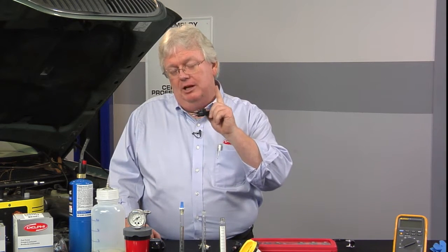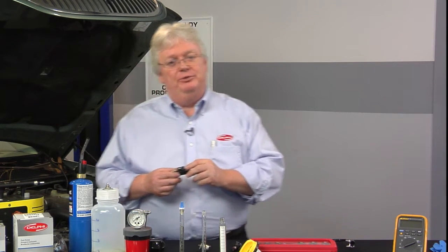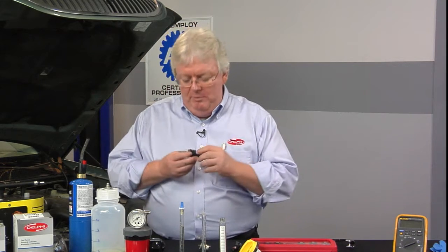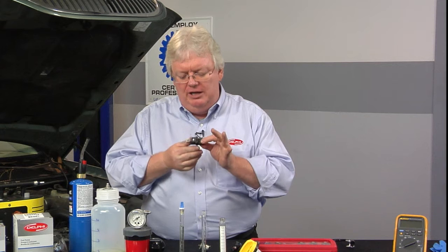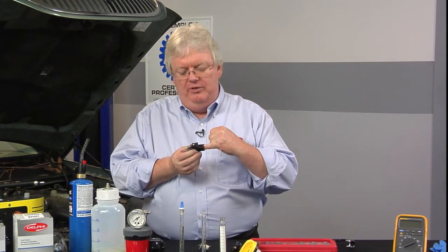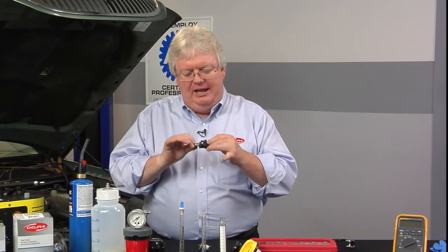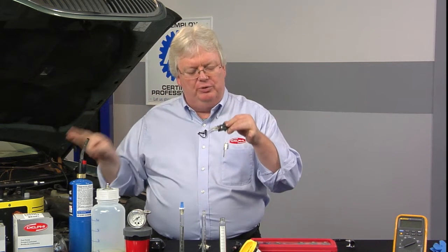Air fuel sensors are pretty reliable, number one. Number two, when they go bad, they usually code. There's usually a DTC specific to an air fuel sensor problem. Now, one thing I will mention about them, I don't have the rest of the sensor. I just wanted to show you the connection right here. This is the connection to the harness. This is the connection, of course, I clipped off of the actual sensor.